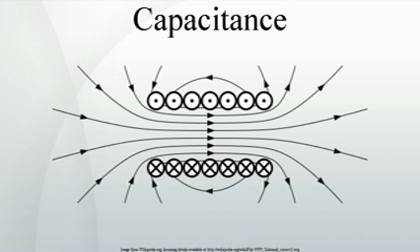Another example of frequency-dependent capacitance occurs with MOS capacitors, where the slow generation of minority carriers means that at high frequencies the capacitance measures only the majority carrier response, while at low frequencies both types of carrier respond. At optical frequencies, in semiconductors the dielectric constant exhibits structure related to the band structure of the solid. Sophisticated modulation spectroscopy measurement methods based upon modulating the crystal structure by pressure or by other stresses and observing the related changes in absorption or reflection of light have advanced our knowledge of these materials.